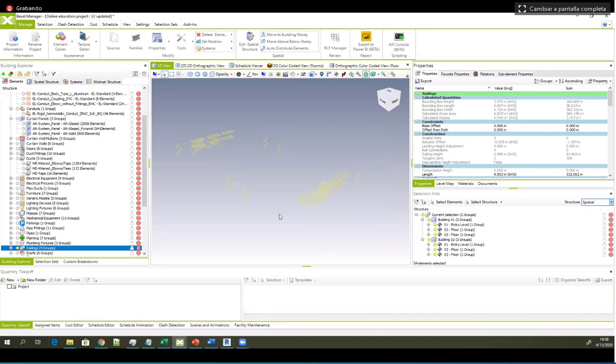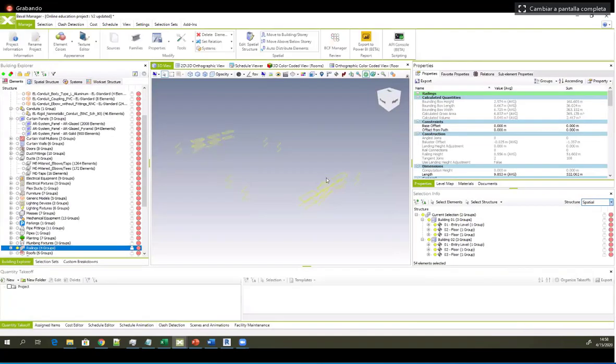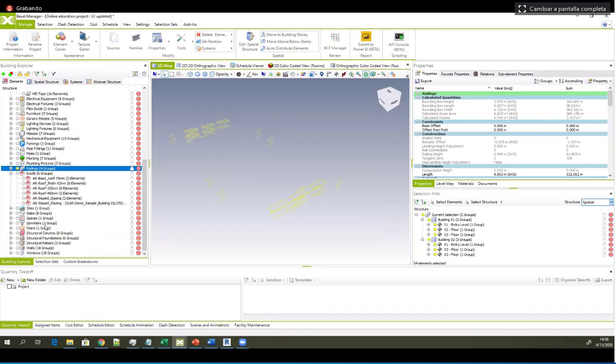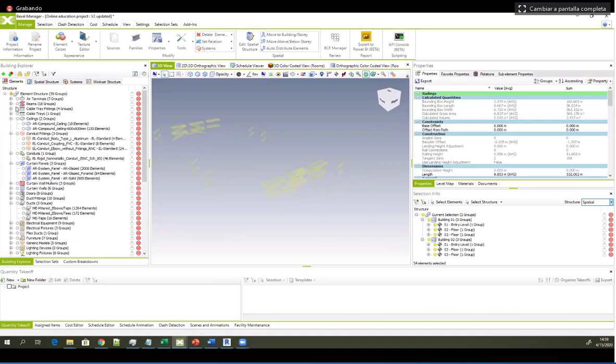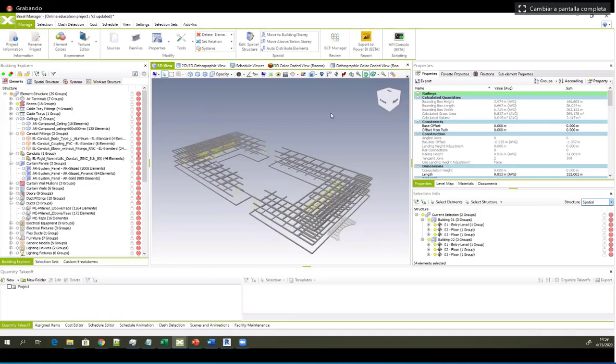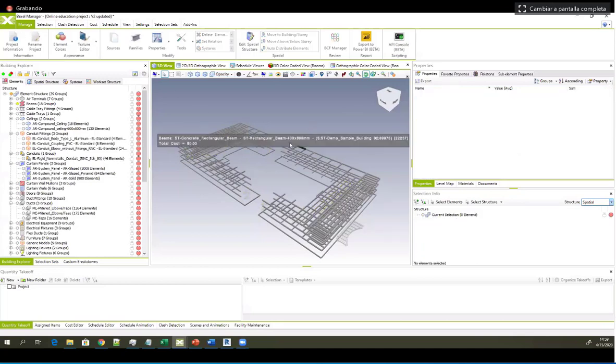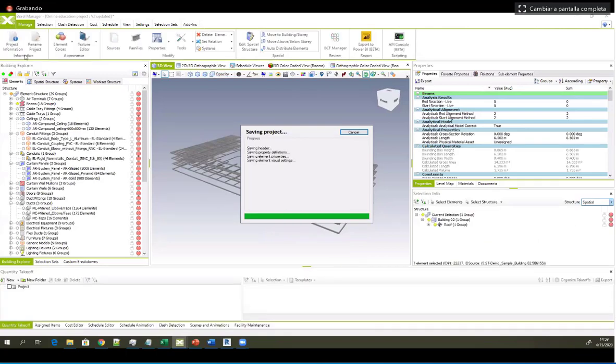Of course, the best way is now, since we have the export IFC option, if you edit some additional properties, you can export IFC files using the option to export elements to IFC. So in this case, in order to make it much faster, I can just export our, let's say, structural beams and these elements we added property for the railing. So I'm just gonna select the beams again. So these visible elements, just in order to make it quicker to export, we're gonna export only these elements which are currently visible to see the consistency of added properties. Before that, I'm gonna save the project and use the option export to IFC.